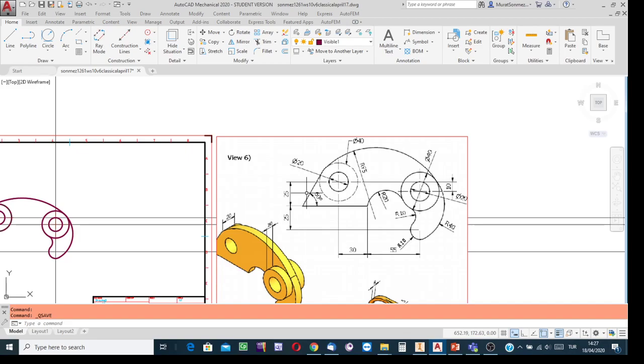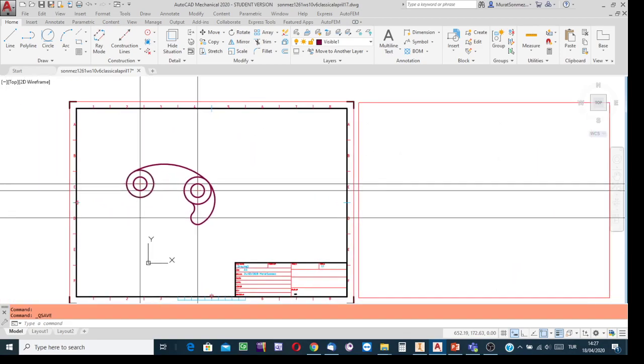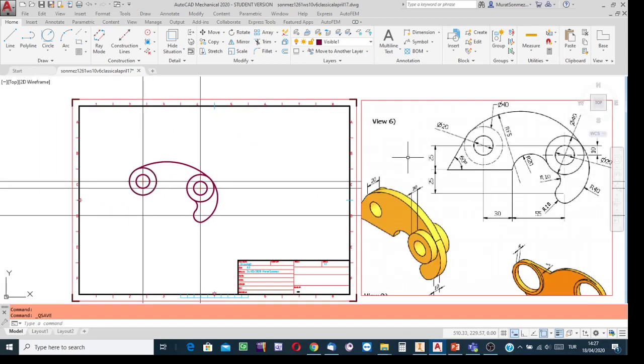should know 4 tricks. Okay, the first trick is the same trick, no matter whether the tangent line has only one tangent point or 2 tangent points. What is that? Start the line drawing process. After starting the line drawing process, change the snap configuration. Enable software to indicate tangent points only. It is the first trick.